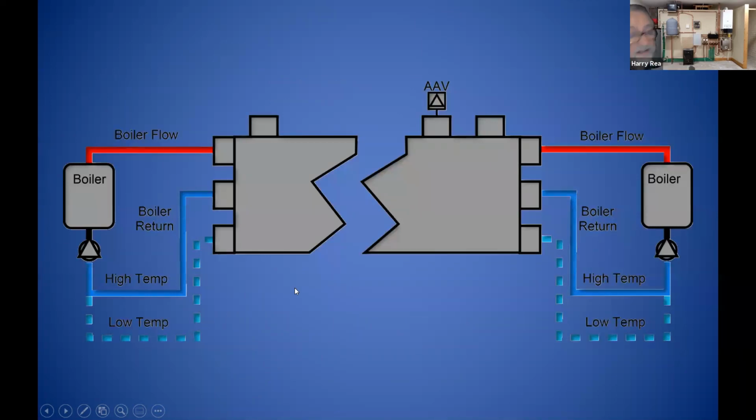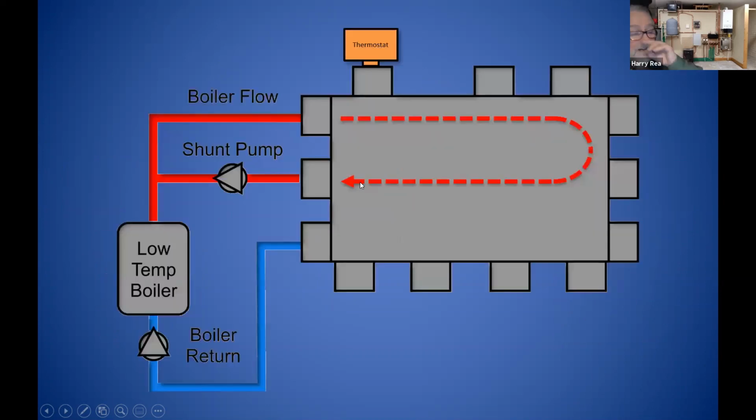You can have a boiler left or right, it doesn't matter how many zones. You always put your vent on what I class as the middle connection on top, albeit that it's over at the right-hand side, because that's where the air trap is. Never, ever, if you're going to take a zone off that, which you can do, you must have a vent on it as well. So here's a very interesting thing.